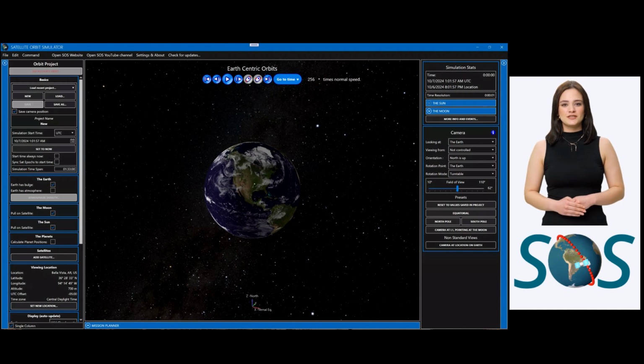A sun-synchronous orbit is one that precesses slightly less than 1 degree per day due to the Earth's bulge. This precession is in a direction to keep the orbit plane constant relative to the Sun's direction as Earth orbits the Sun. If the orbit plane is approximately perpendicular to a vector pointing toward the Sun, the Earth satellite will always be in sunlight, regardless of where it is above Earth.